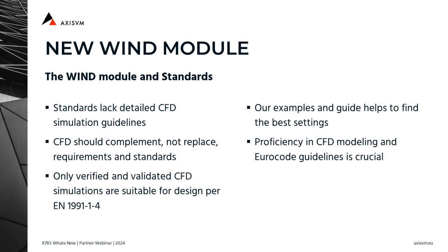However, none of these standards provide detailed guidance on conducting CFD simulation. CFD simulations should be used in conjunction with building regulations and standards, not as a replacement for them. According to the Eurocode, structural design should be based on validated and verified numerical CFD simulations. Our validation examples and descriptions serve as a useful resource for finding numerical settings aligned with the standards.